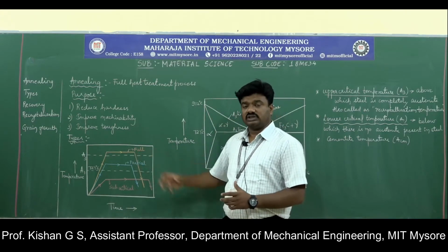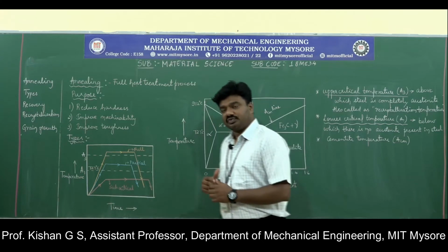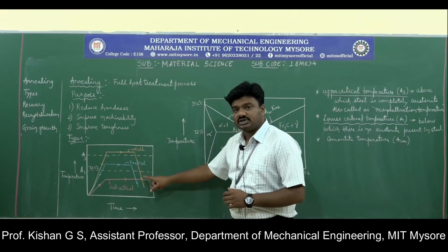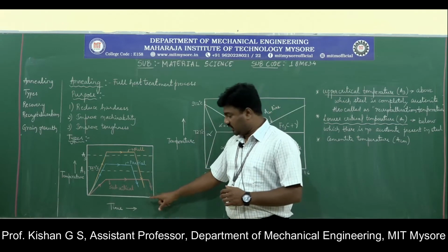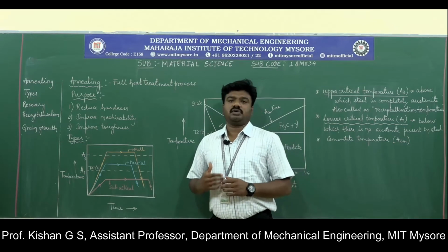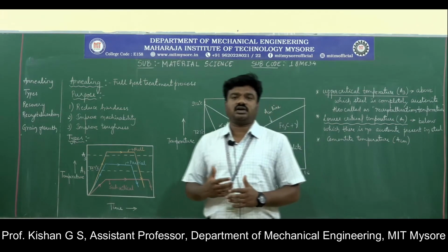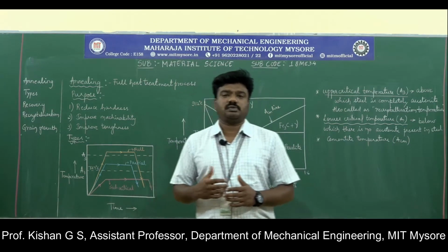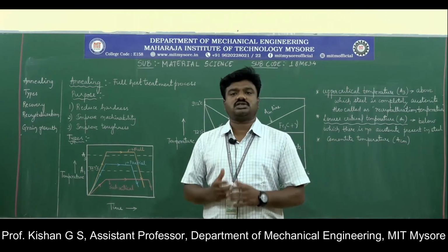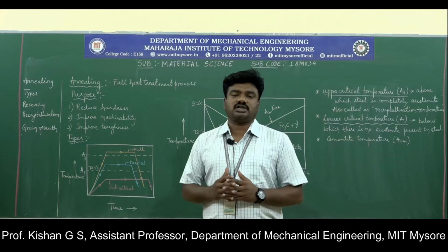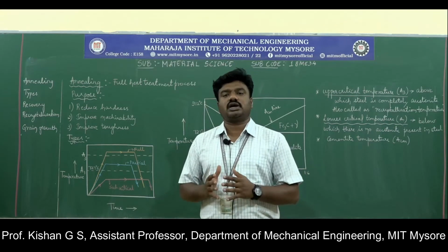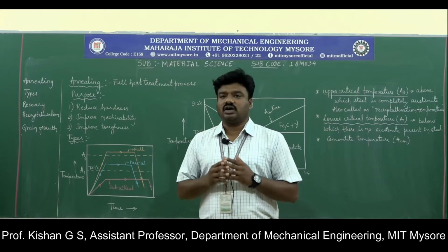Once it is kept for a period of time, we concentrate on reducing the temperature of that composition. Again, this reduction is also with respect to time. You can consider a very fast reduction in temperature, maybe by quenching, but in the annealing process a very slow cooling rate is employed to bring the material to room temperature, so that the final part is ready.